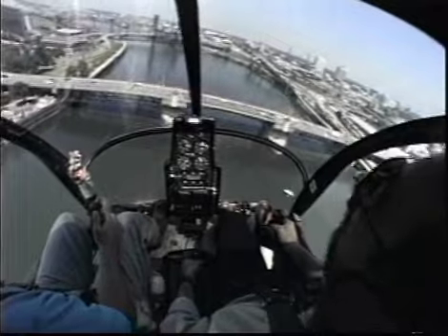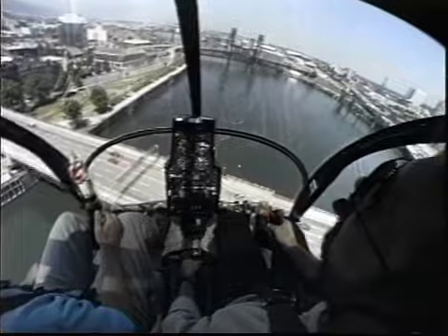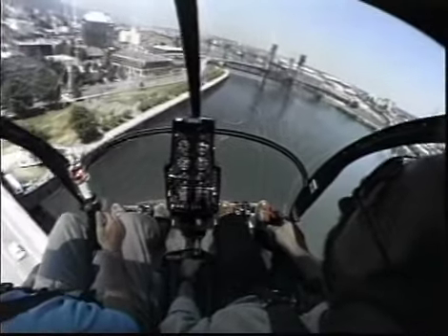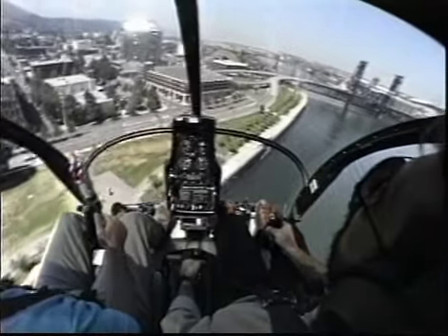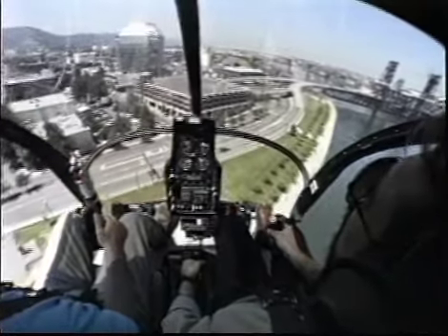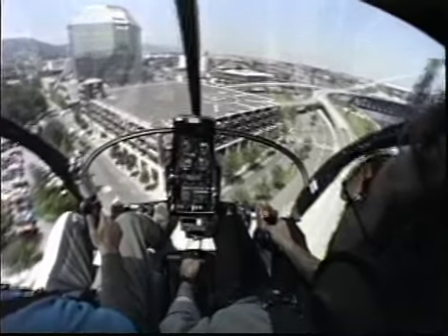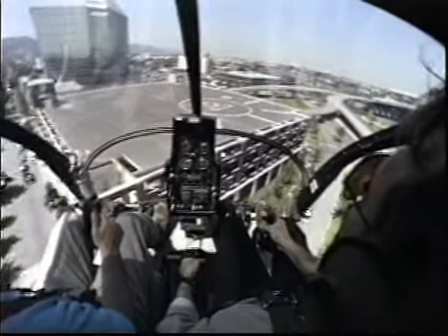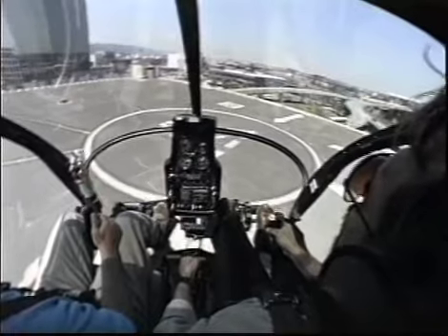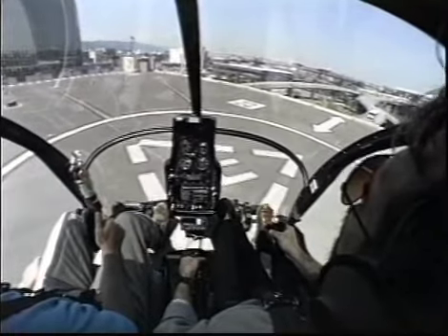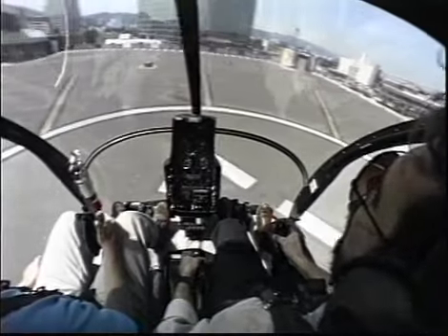You'll often find tricky winds on rooftop heliports. The location and proximity of buildings, bridges, and other obstacles creates winds whose direction and turbulence can change dramatically in just a few feet. Some rooftop heliports even have 2 windsocks, one each at opposite corners. If downdrafts and turbulence are expected during a pinnacle approach to a rooftop heliport, plan to make a steeper than normal approach. Use the collective to maintain the desired descent angle. This approach technique reduces the chance that a sudden downdraft might push the aircraft too low.